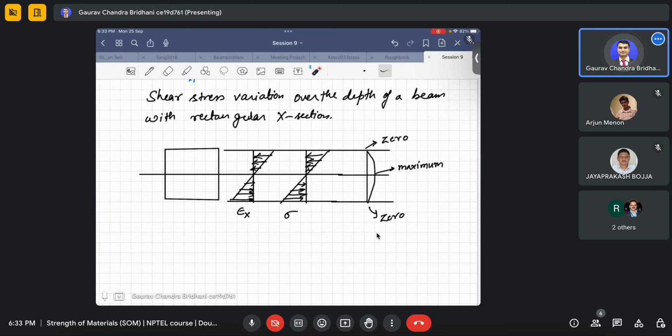So even though the shear will be there and we design for the shear, while calculating the deflection, which you may see in the next session, you will find that the deflection due to shear we very rarely take. In the case of slender beams, we never calculate the deflection due to shear, because as you saw the contribution of shear stress is small, so the contribution in the deflection is also very less. It is within 5%, so we tend to ignore it.